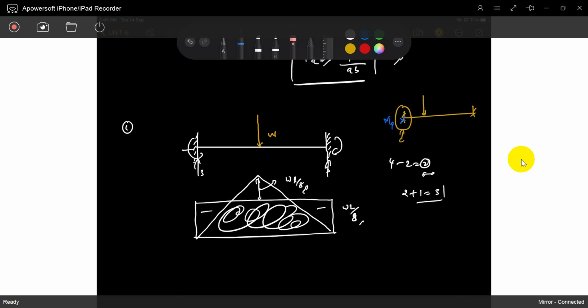Later, where another maximum bending moment is acting at another location, you can take it as this location. So next MP is formed here. Once it reaches the MP, it is a hinge. But if you form the hinge here, it does not enter into the mechanism, because the fixed joint is there and the load is acting. It is a proper cantilever, which has one indeterminacy.